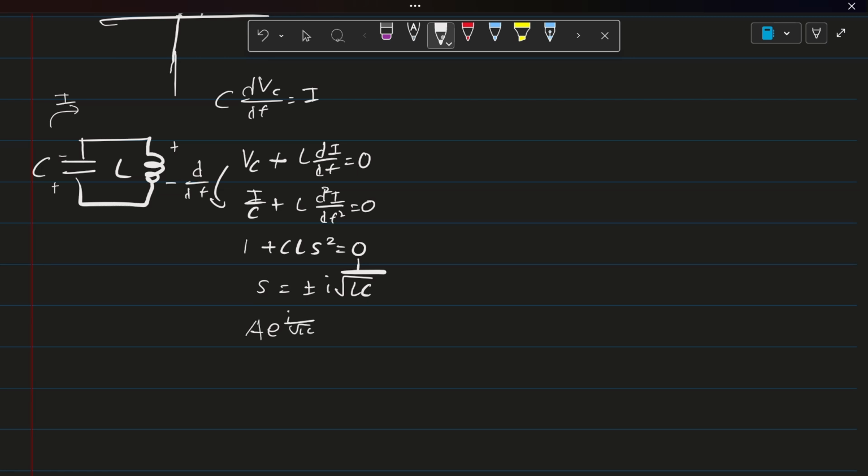Multiply that by A, in which A is a complex number, let's say. So this describes pretty much a cosine, so it's A times cosine of t over the square root of LC plus phi, or the phase difference. And so you could actually have any type of A as well as any type of phi to be the solution of this problem.